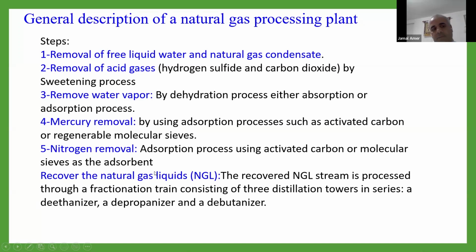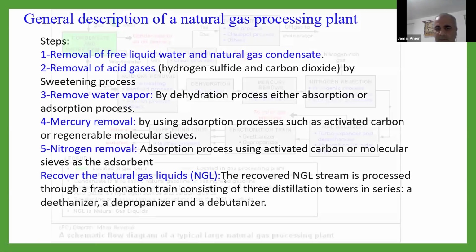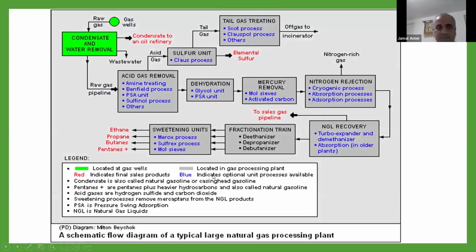This is also one process of gas treatment. Okay, this recovers natural gas liquids, NGL. This, as I told before, is a byproduct of natural gas. So C1 is exported, while these have further treatment through a fractionation system.